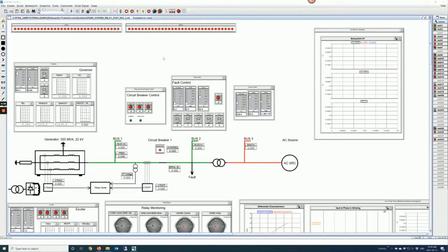At this part of the presentation, we're going to show the runtime simulation of the case that we've shown in the draft, generator protection and excitation. Let's hit play. If you remember, the goal of this simulation was to start the machine from 0 speed and 0 excitation and synchronize the machine to the network and close the breaker. Once the simulation starts, you'll see that speed starts from 0 and reaches its rated value.